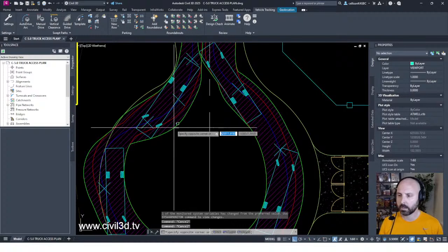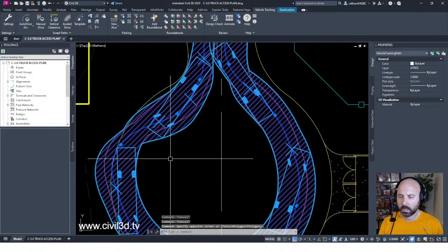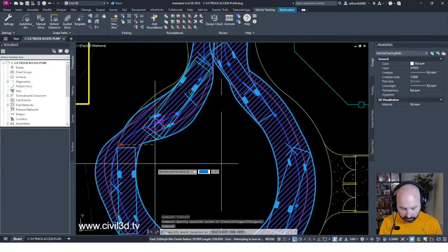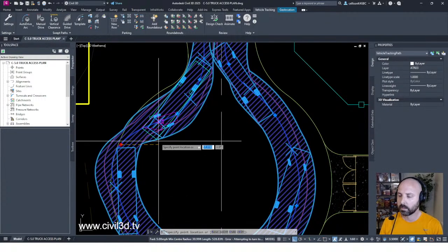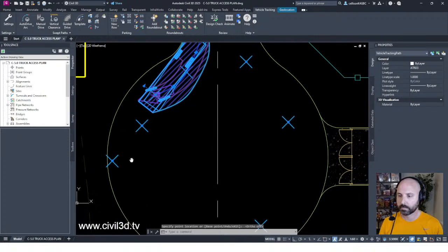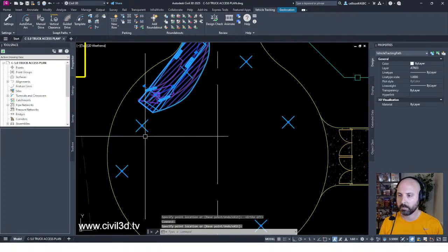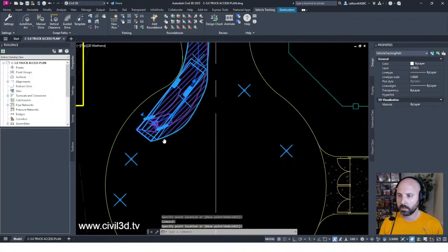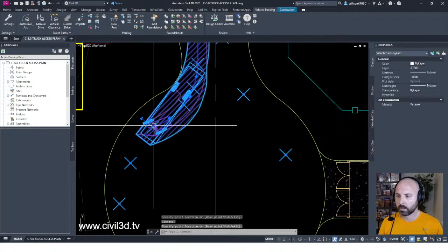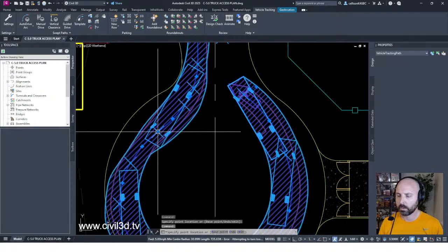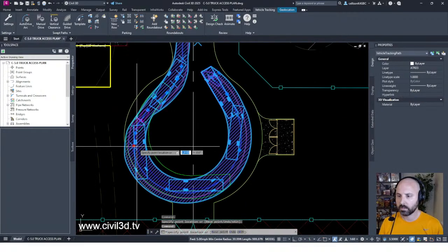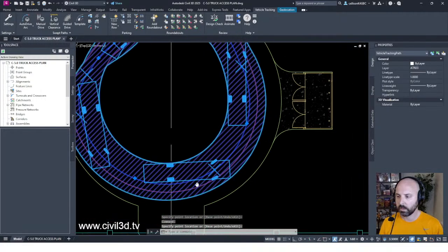I'm going to come in here and adjust. Oops. It looks like ortho is on. I want to turn ortho off by pressing F8. And you see that it was a little too extreme. It was too extreme, man. We'll move this over. There we go. That's working. Just making small adjustments to those little X's right here.